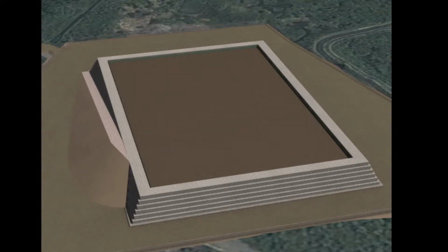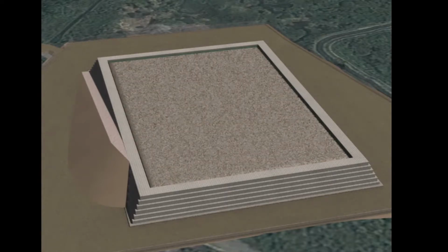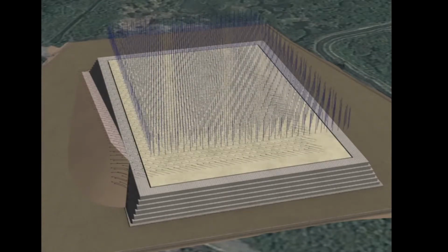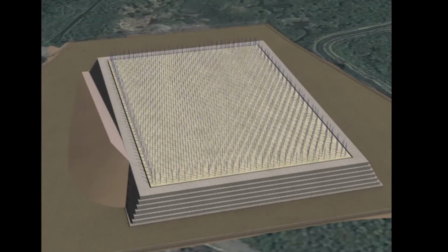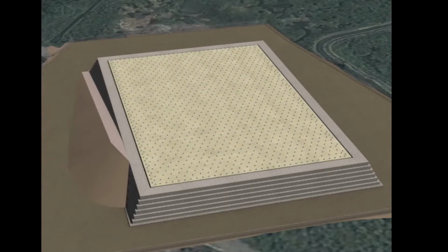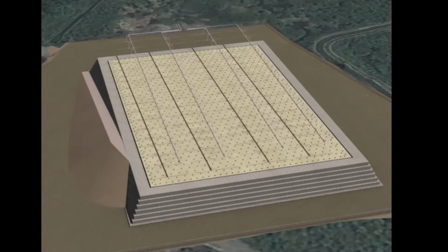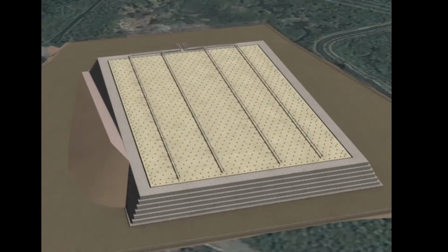The second phase, scheduled to conclude in 2016, largely involves excavating and treating sediments from the northern half of the site. After the structure is filled with soil and sediment, it is covered with a layer of gravel and an insulating concrete cap. Approximately 1,250 heater wells are then inserted into the pile. The heater elements inside these wells are critical to the remedial technology and are responsible for heating the contaminated soil and sediment. A horizontal vacuum extraction system, which maintains negative pressure, and air injection wells, which ensure adequate oxygen supply, are also installed.